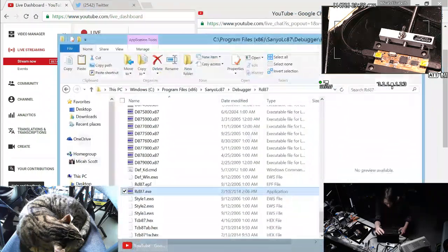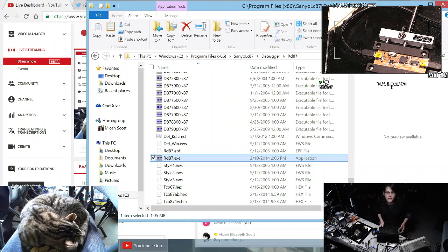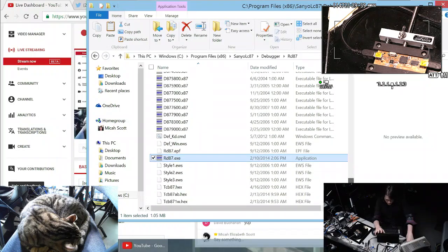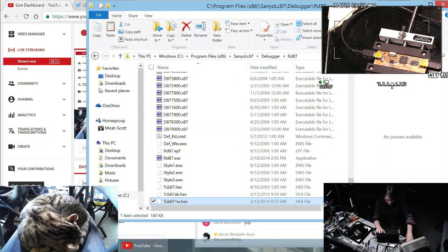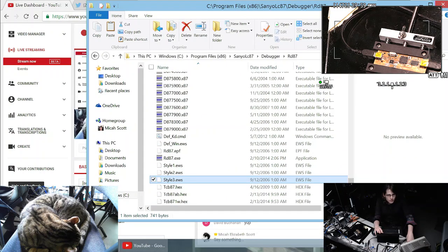Okay, so I think the way around this was to actually just implement that firmware read and include a copy of that TCB87w.hex. So we might actually just be able to do something similar. I forget whether I think I had converted the hex to a binary file. I might do a quick check to see if there are any convenient Python modules for reading these Intel hex files. I feel like I've looked for Python code for reading these before, and I might have ended up just using something that I wrote in the past.